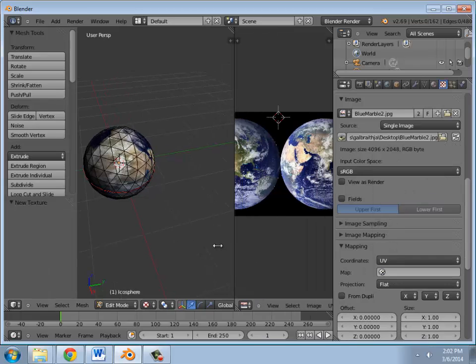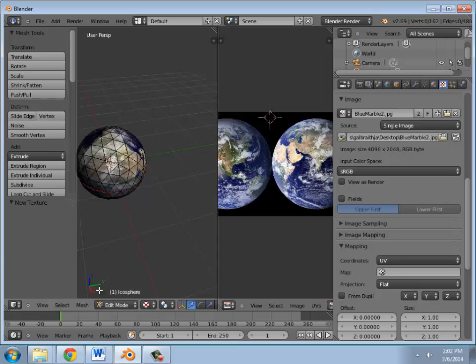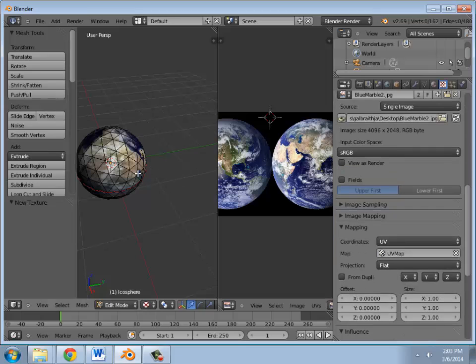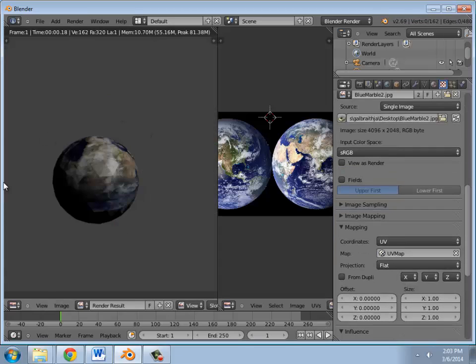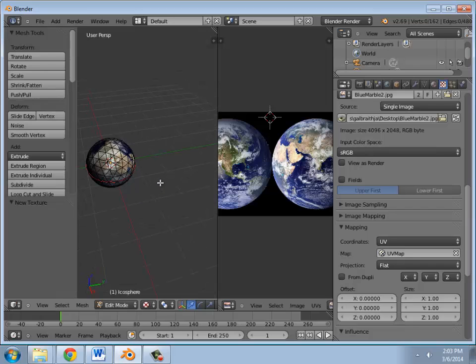By the way, you may be wondering, UV, where does that come from? Well, you have X, Y, and Z over here already. What are the two coordinate things over here? Well, it kind of ran out of letters, so this direction is the U direction, up and down is the V direction. So it's mapping points in the UV plane to points in the XYZ plane, hence UV mapping. So I'm going to take that particular mapping, so the UV coordinates, UV map, and then the projection. Ta-da! Now it renders. That's the basic idea with this particular project.